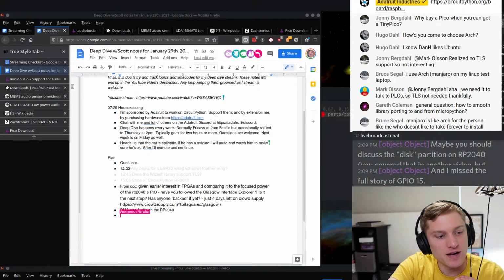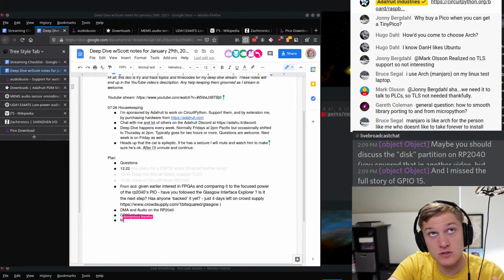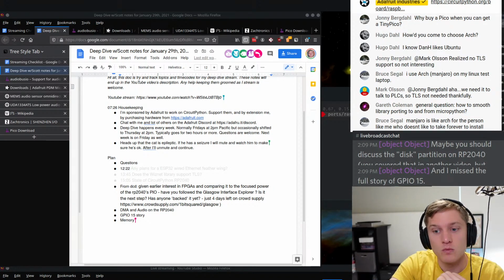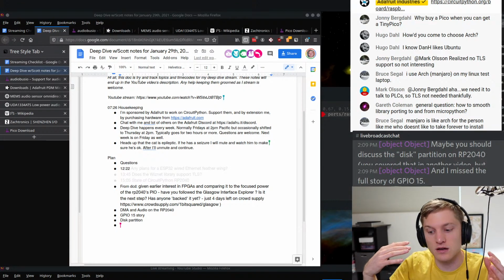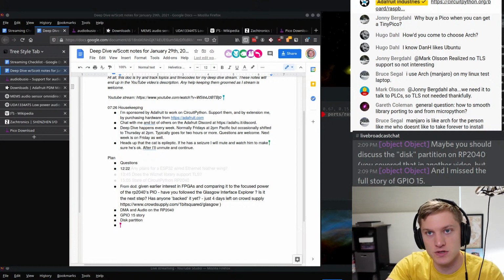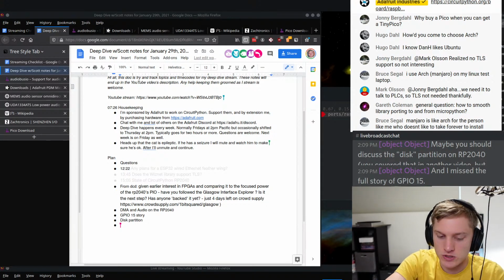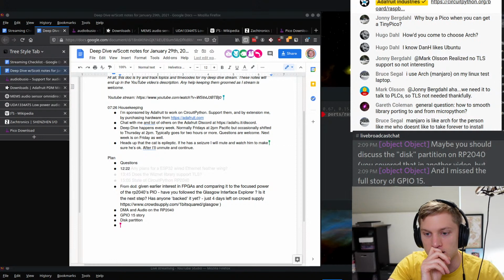Let's see. API wise, I was gonna do UART, and so we have RP2040 for the PIO. What's missing there is we only have write implemented right now. We can't read from it. And the reason is that I was focused on supporting NeoPixel. So we have NeoPixel. It works with PIO under the hood, so you don't have to instantiate the PIO yourself if you want NeoPixels. It works like any other NeoPixel. Yeah, so there's work to do on PIO to get reading from it.